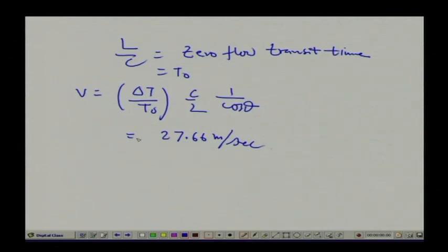Now, we see that there is a percentage change in the velocity of sound. How will my measurement be affected by that? So, let us look at that. Initially, when there is no change, that time I describe with T1. So, delta T1 equals 2 V cos theta into L by C1 square, right.